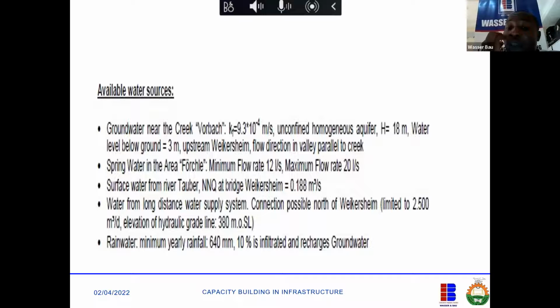You now use a filter. When I say filter, the simplest filter is sand. Well-graded sand anyway. Rapid, slow sand filters. You now use the filter to filtrate them because they are not soluble. Sometimes you can even decant them. When they pass through the filtration bed, they can't pass through those filters. So the clean water will flow out.